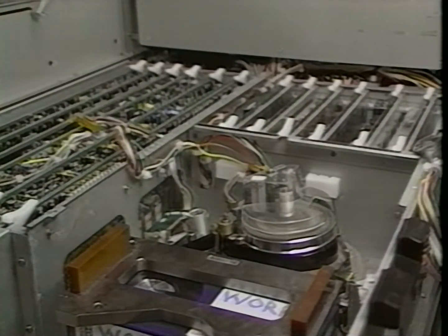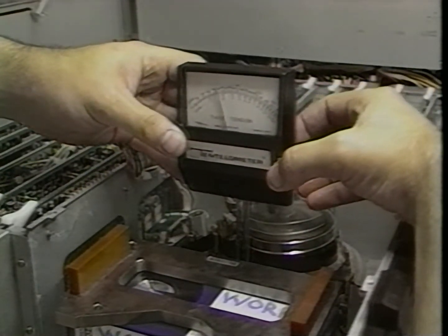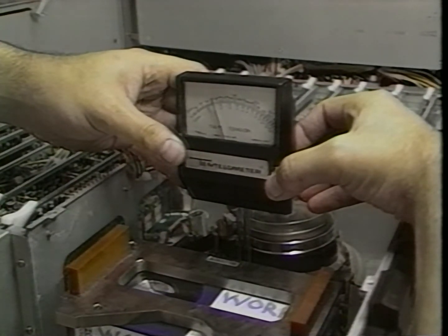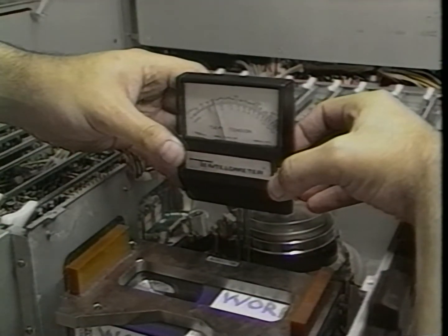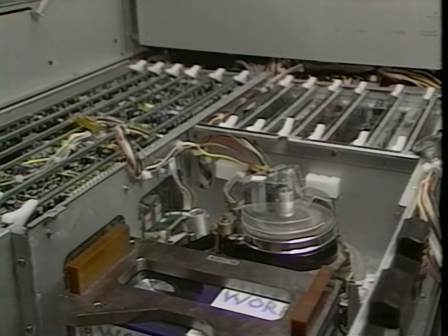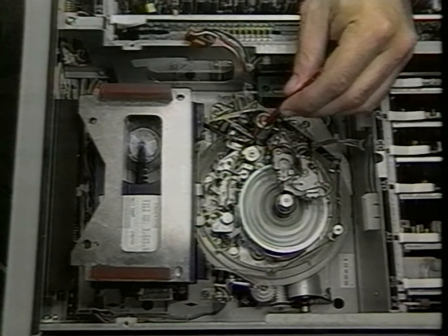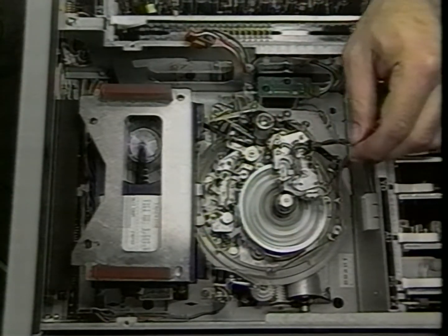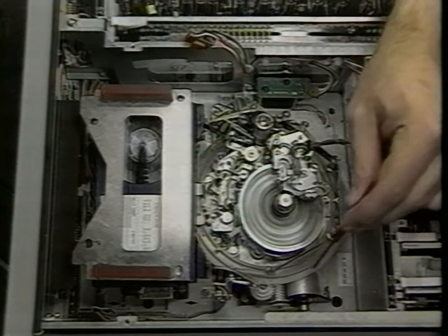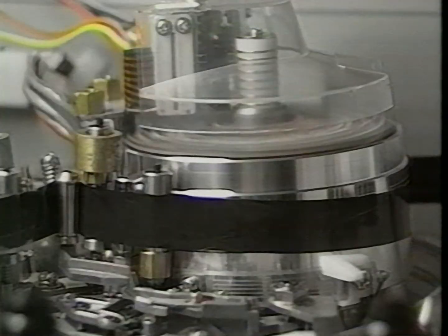The first step of the tracking procedure is to check the tension of the tape path. The playback transport specification is 45 grams at the entrance of the scanner. This specification can be measured with a tensionometer or a tension scale. The tension regulator operating position and forward back tension adjustments should be performed to meet the specification. In addition, the tension should be equal at the upper and lower edges of tape around the rest of the threading ring. This is specified by the tape run adjustment procedure listed in your manual.